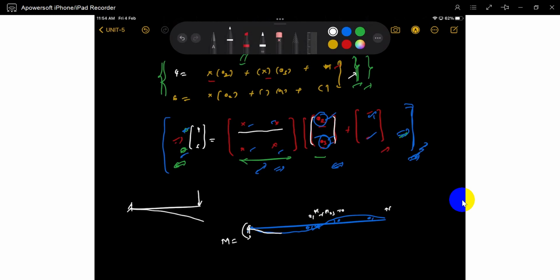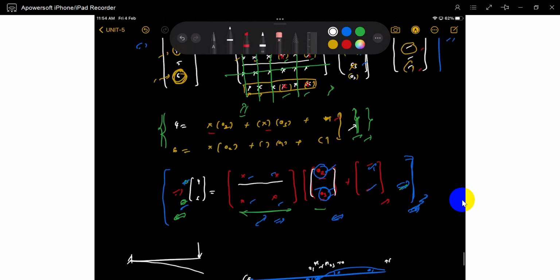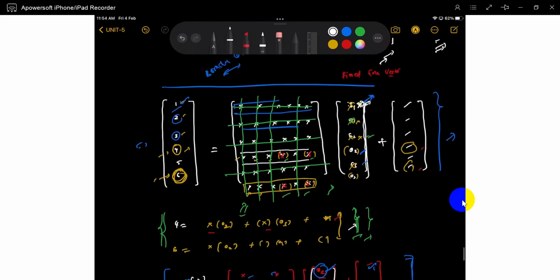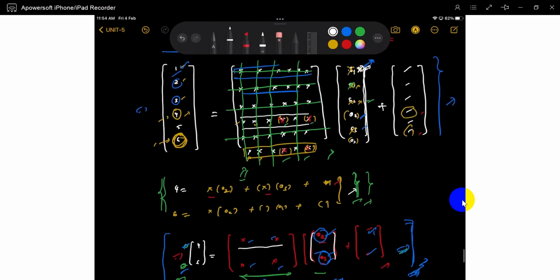There is no support, there is no reaction. If support is there, there will be a reaction. The moment the deformations are restricted, the forces will be generated. The force is generated means the deformations are restricted somewhere. That is a beautiful line. So by this, the boundary conditions, you can directly come to this slide.